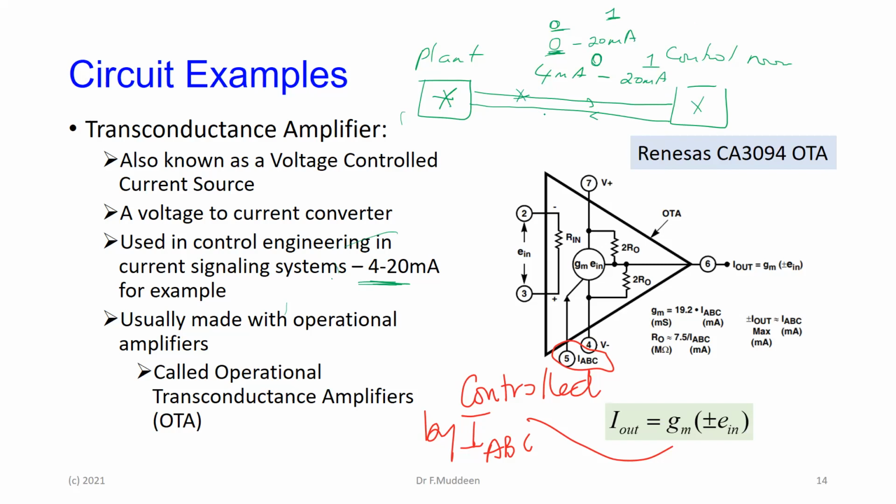If the wire is damaged, I also will get 0 milliamps being detected in the control room, right? Or if the wire is short circuit and the current is going to ground, then the control room on the other side of the short will be seeing nothing. In that case, you can't distinguish a valid signal from a short circuit or open circuit.